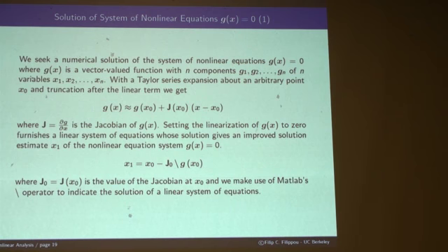As a result, competitive methods, whether they are known as Krylov methods, we're going to hear about that, or whether they are known as BFGS methods or other iterative methods, avoid forming the stiffness matrix J and try to update the solution by some other means. Right? They use the matrix occasionally, but they don't use it all the time. All right. So keep that in the back of the mind.